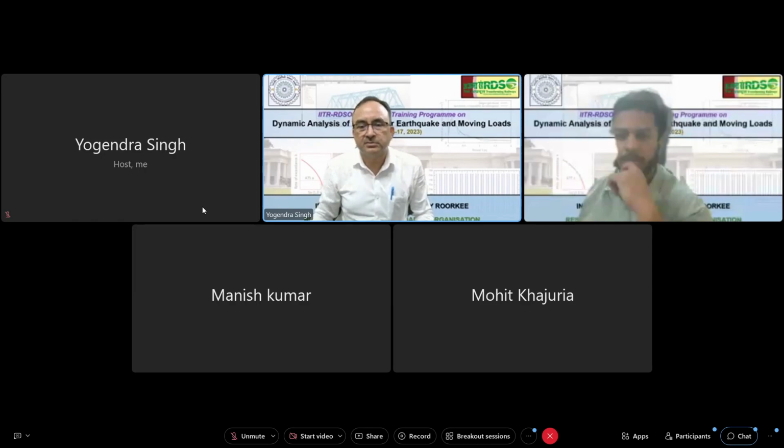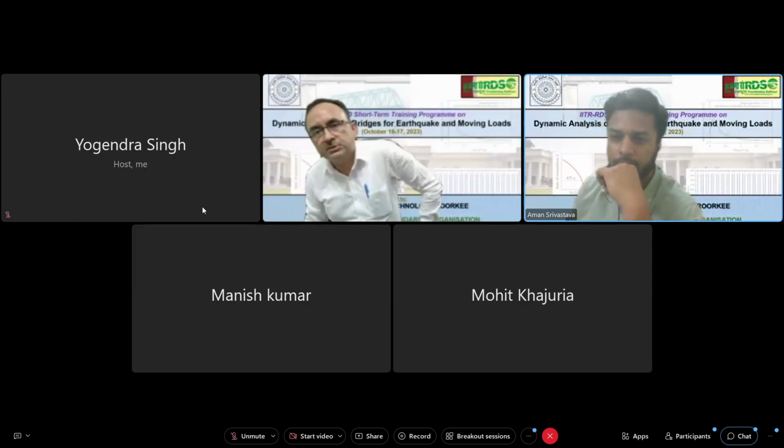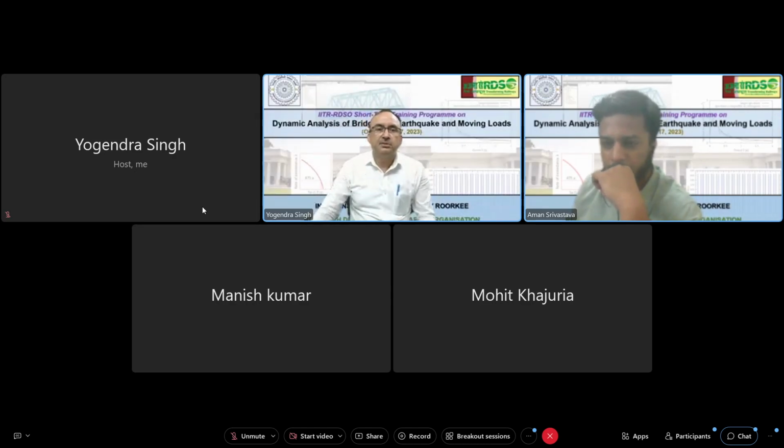Sure, sir. Mr. Suraj is asking, if in the response spectra of IS 1893 2023, the period of ZPA is 0.01 second, does it mean we can consider the modes up to having frequency 100 Hz for 90% mass participation?